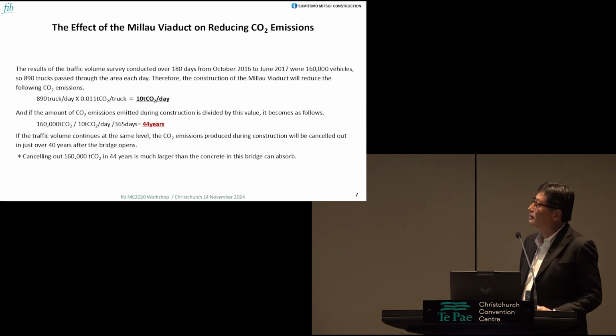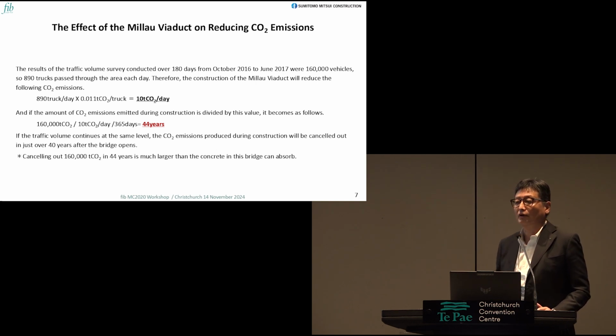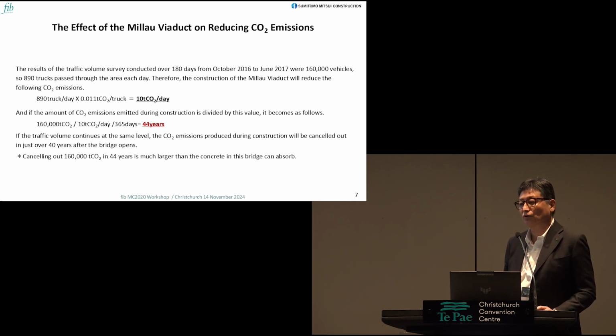Finally, the CO2 emission due to the construction divided by this value means 44 years. So after 44 years, roughly speaking, the construction-emitted CO2 is compensated to zero. So 40 years is not so long compared with the CO2 absorption by the concrete in this bridge. So this kind of estimation in the design process is going to be a very important issue in the near future when the designer and the client make decisions in the design process.